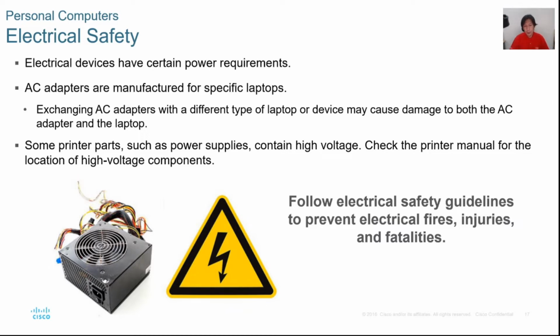Also, our printers have parts that contain high voltage. For our safety, we need to check the printer manual for the locations of those high voltages. The main parts of concern in printers are the print head for an inkjet, and for a laser printer, mostly the drum circuitry, the drum part of the laser, which has the higher voltages.